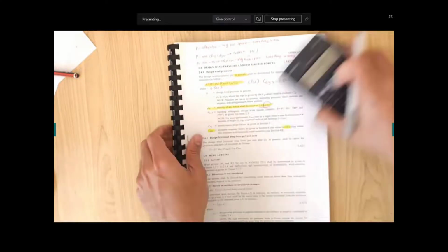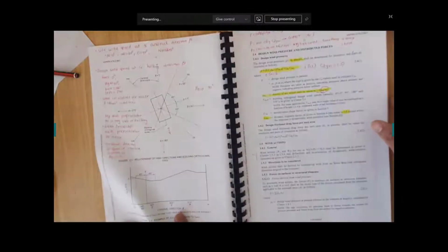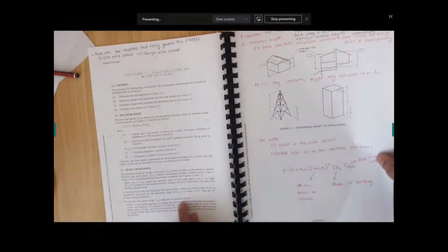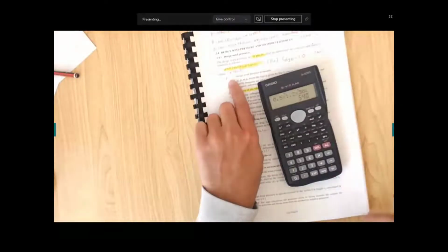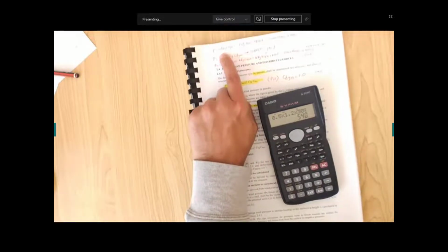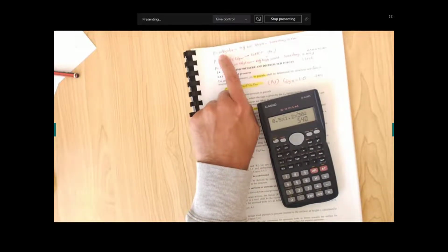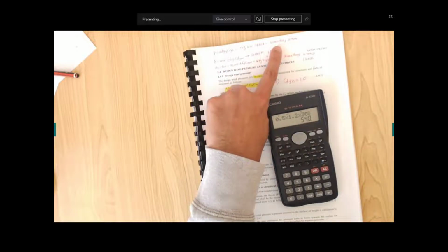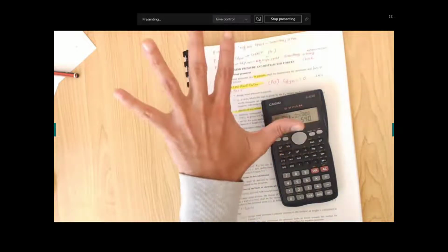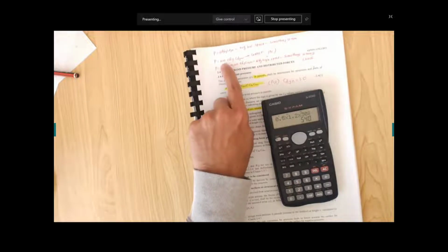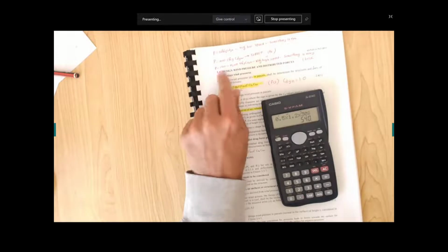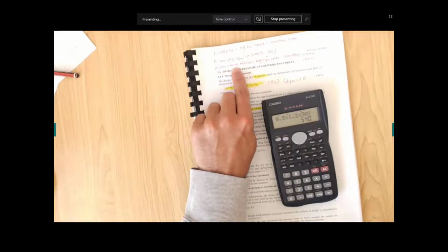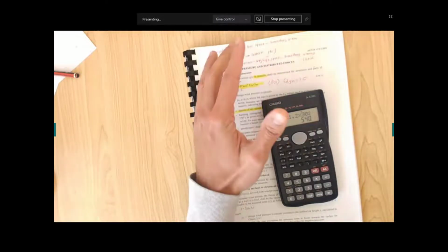This is given in the standards. I can show you again that this never be less than 30, regardless of that. That is 30 written here. So for that case, if I at least put 30, you have 540. So 50 is too low, right? Your velocity would be less than that. So something is wrong, go back and check it. Around thousands, yes, it's okay. If it is thousands, meaning that you have 540, up to thousands, it looks okay. If it is 1500 to 50,000, there is something wrong, very high speed.